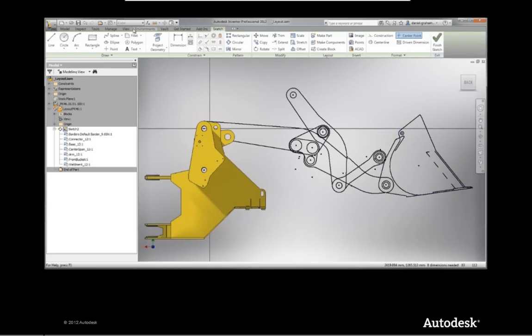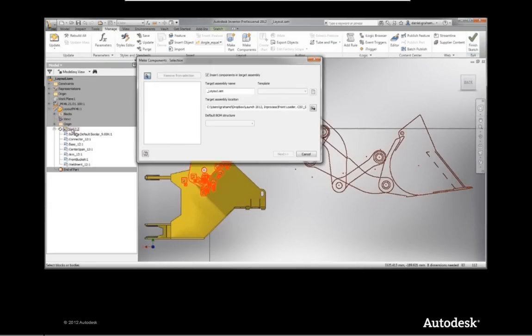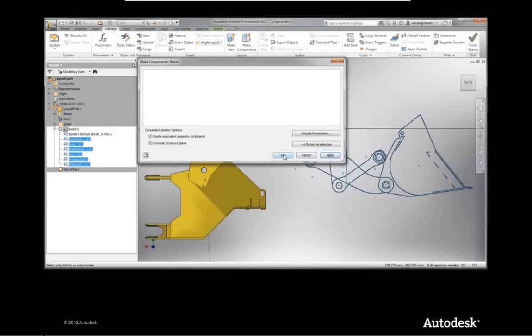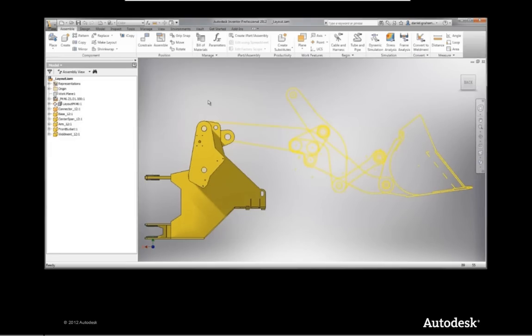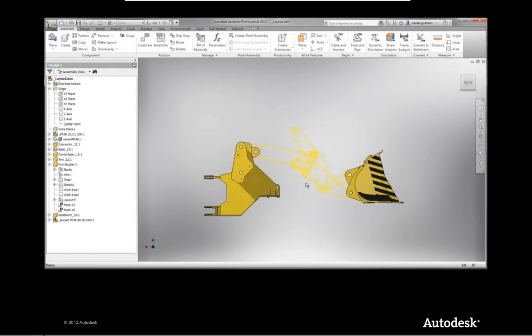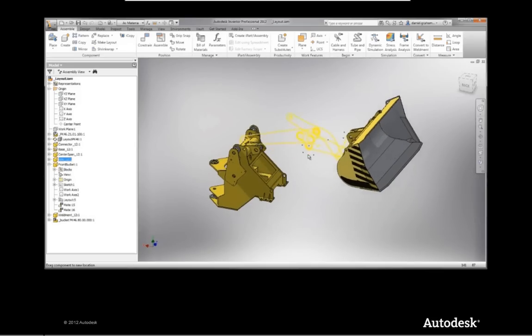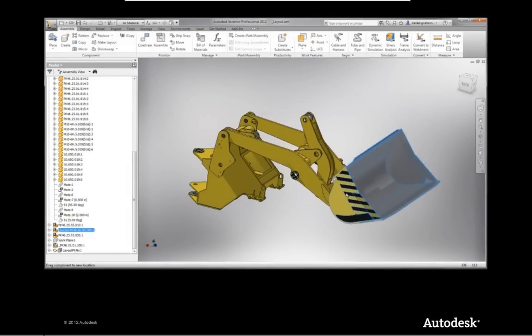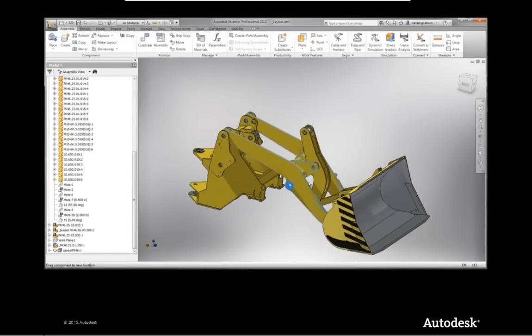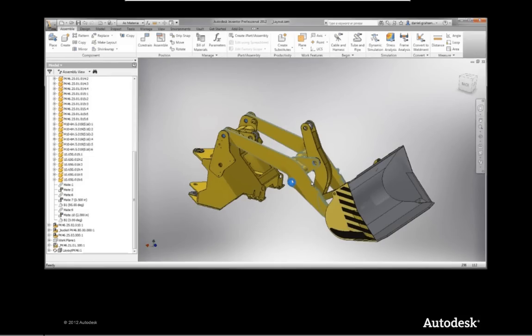3D. We can then push these blocks out to parts in an Inventor assembly. And then once we push these out to an Inventor assembly, we can then extrude and model in 3D our parts that came across as blocks initially, and convert these to 3D parts in our assembly, and we've got our final design. Obviously, if we go back to the 2D geometry and update it, then our assembly will update automatically.